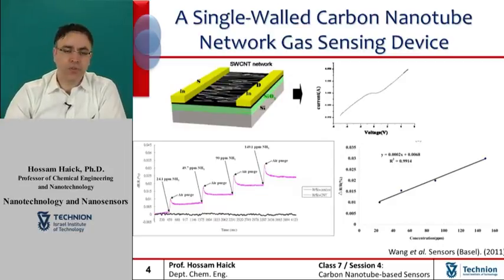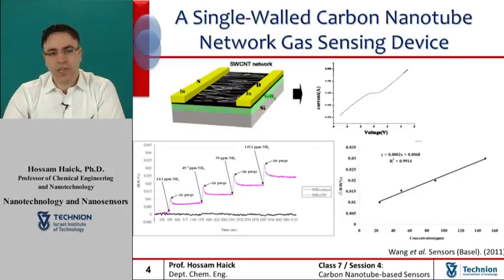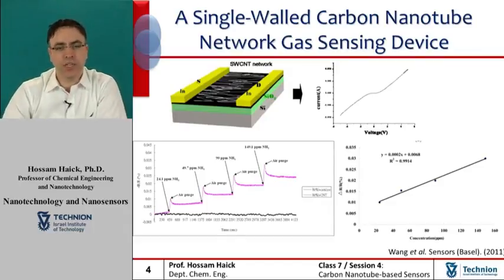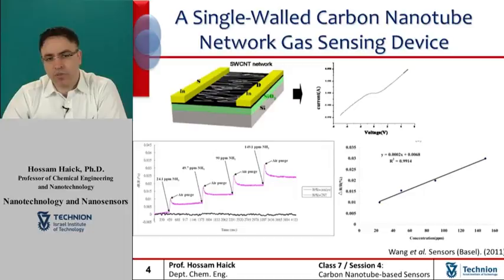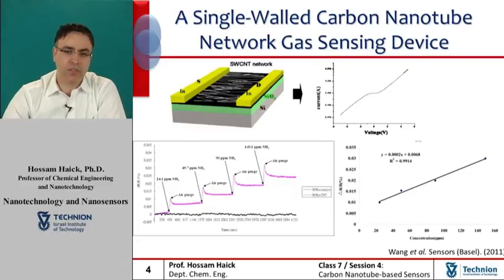In the case presented on the screen, interconnected single-wall carbon nanotube networks are exploited to recognize the identities of different chemical gases by the strength of their particular surface adsorptive and desorptive responses to various types of chemical vapors. The physical responses on the surface of the single-wall carbon nanotubes cause superficial changes in the electric charge that can be converted into electronic signals for identification.